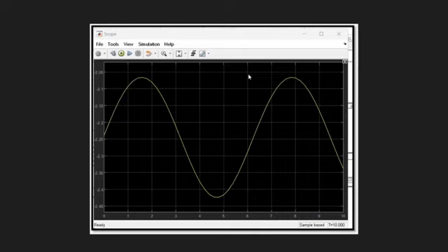It is observed that the blade element closest to the hub height, r equal to 5 meters, experiences a longer duration of tower shadow. However, at theta equal to 180 degrees, that is the blade directly in front of the tower shadow, the same wind effect is seen by all elements of the blade.